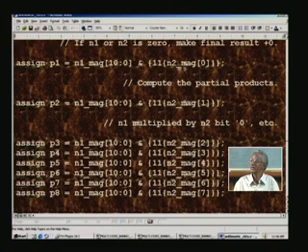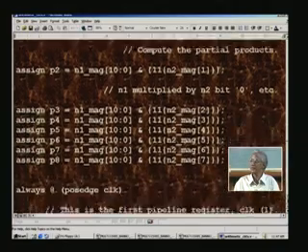If it happens that one bit is 0, all 11 bits will be 0, because it is a concatenation of all the same bits. So if the first bit of n2 is 0, naturally the final result must be 0 for all the bits. If it is 1, all will be 1 here, and therefore you will get exactly n1 repeated and copied, assigned to P1. So is the case for all the partial products P1 through P8, and that is what is shown there.